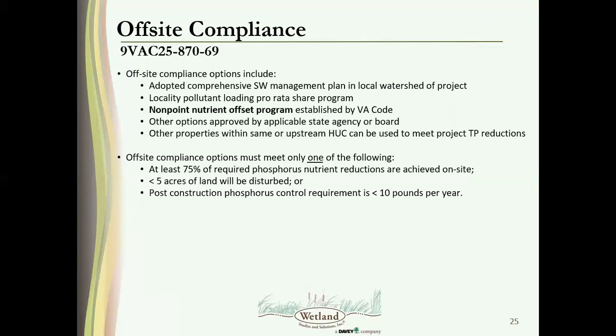Your entire disturbed area is less than 5 acres, or your load requirements are less than 10 pounds, okay? So you don't have to meet all 3 of those criteria, you only need to meet 1. However, you still got to get your approval from your VSMP authority.